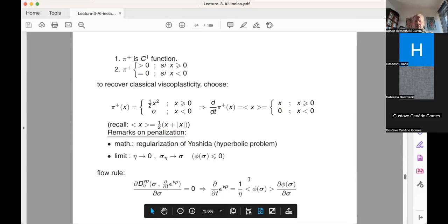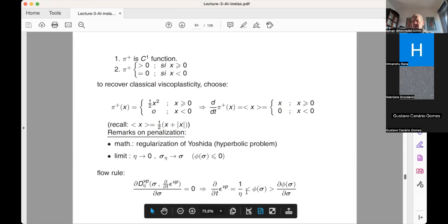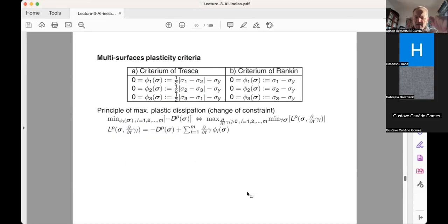Whereas here, as long as you have your stresses and your viscosity parameter, you can obtain immediately this kind of viscoplastic multiplier. In the code, you can actually very easily implement both plasticity and viscoplasticity, just say which version you're computing, and then you can obtain your multiplier in the most appropriate way. So basically, this will be the story about viscoplasticity.